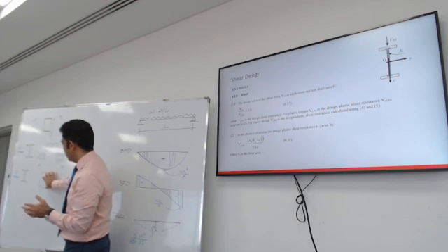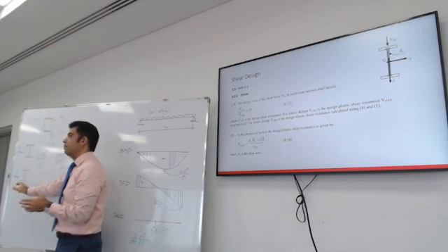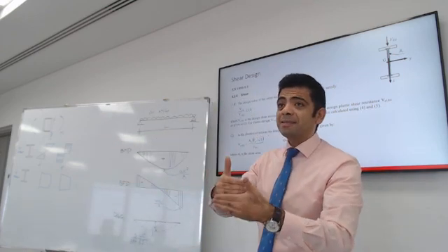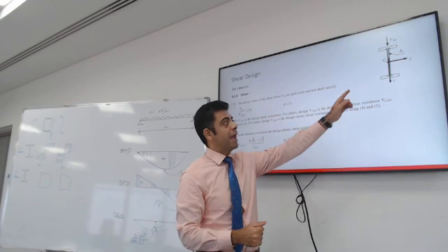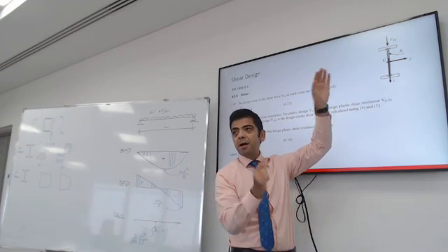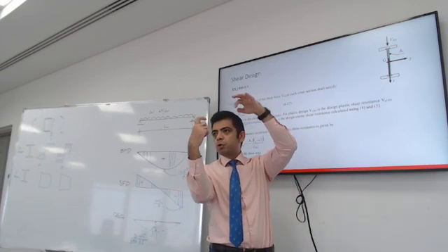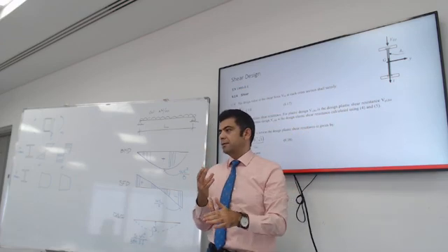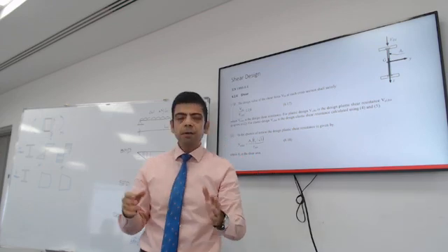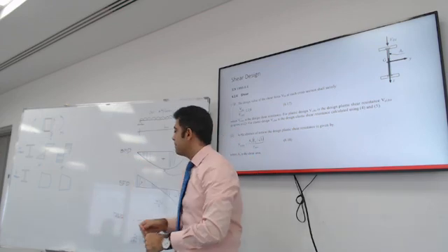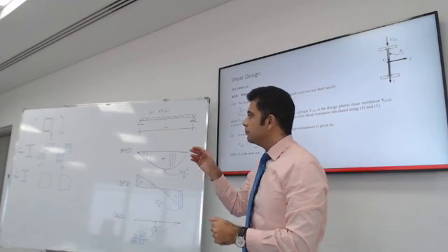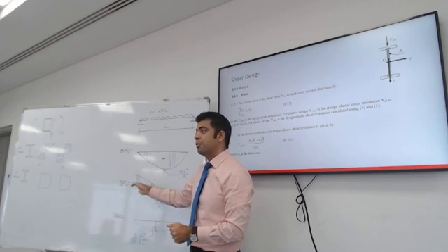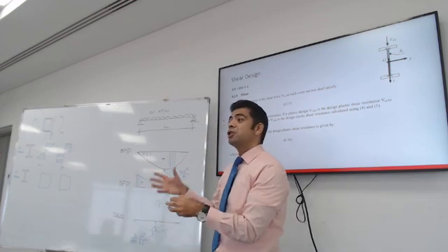So the majority of the stresses are acting on the web. Therefore, the shear capacity of the section depends on the area of the web, the gray area, plus a little bit of excess material, the root, that connects the web to the flanges. So long story short, the Eurocode suggests that the shear force, which you get from the shear force diagram, on the beam is less than the shear capacity of the beam.